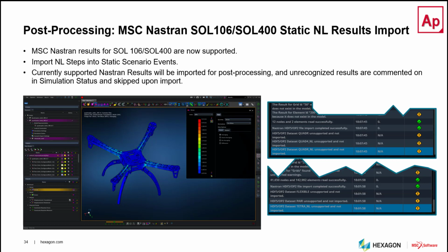The next one is a big new technology, which is we're just now beginning the baby steps of supporting nonlinear analysis inside of Apex. Solution 106 and Solution 400 static nonlinear results, you can now import those results inside of MSC Apex.